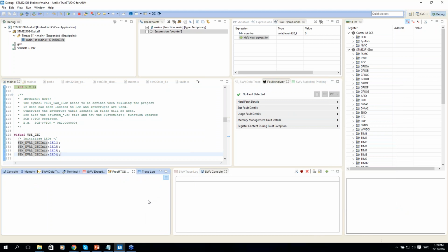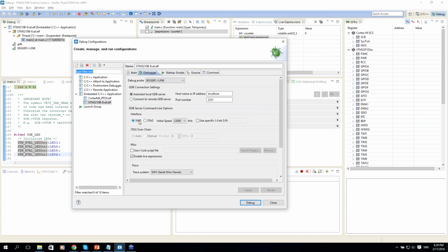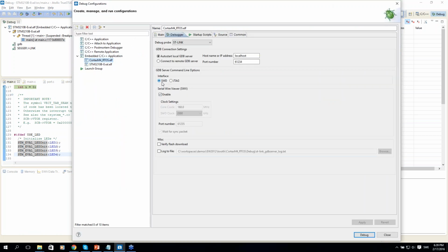Okay. Another question. This just came in. Are you using SWD or JTAG with serial wire viewer? Serial wire viewer requires serial wire debug, SWD. So this is the 2-pin interface, and the serial wire viewer adds a third pin, a trace pin, which transfers data back to the debugger. So yes, the SWD interface is necessary. It only works that way.